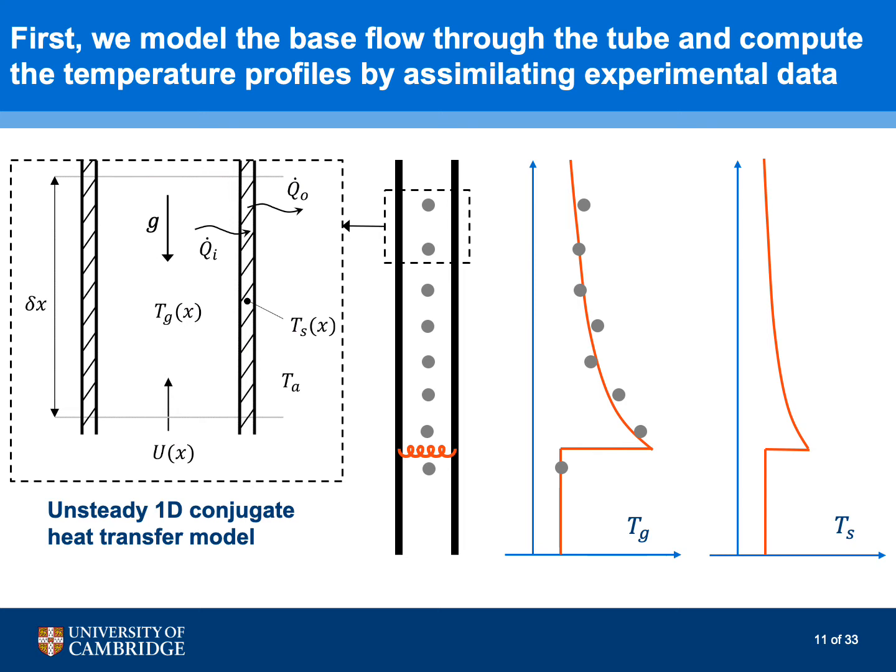These three equations are all coupled between each other and depend on three parameters: two Nusselt numbers that characterize the heat transfer from the gas to the wall and from the wall to the surrounding air, and an implicit loss coefficient that quantifies the pressure loss that occurs across the heater. The model assimilates temperature measurements every 7 seconds, and when it does so, state and parameters get updated.